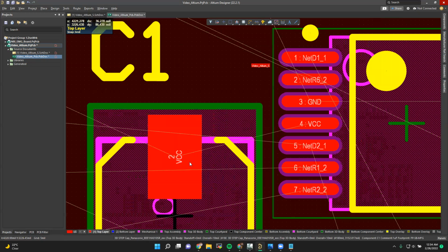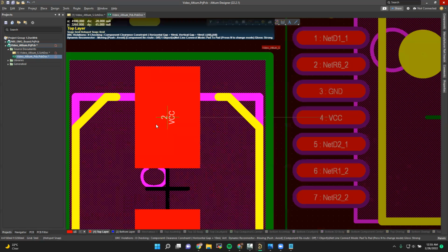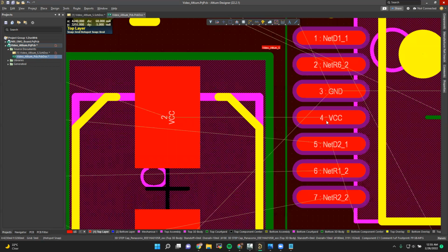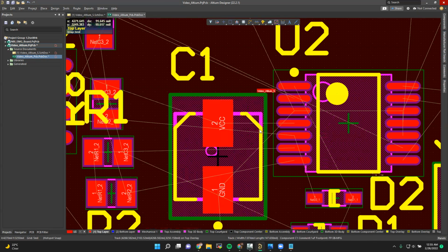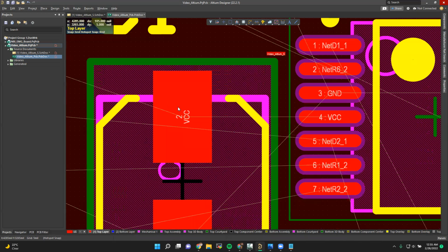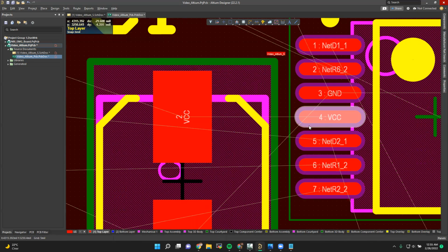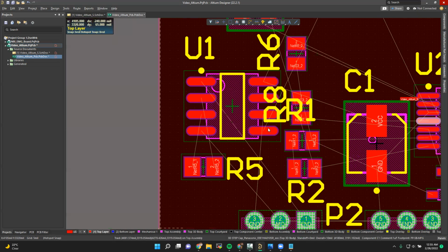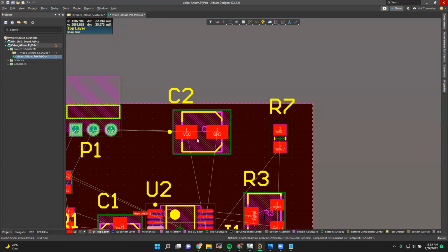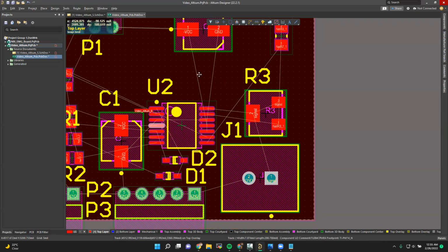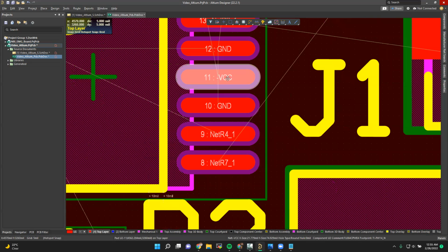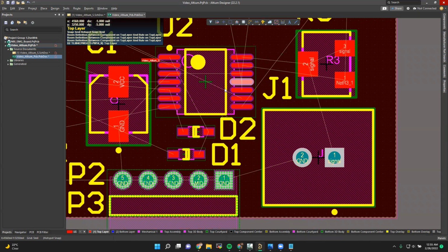So this is going to be better for the design, because you can see now my VCC is here and the VCC is here. So I only need to make a trace from here to here. There's not going to be as much noise affecting the VCC signal. Well, it's not a signal, the power trace going from here to here. The same with this one, the same with this other capacitor. This other capacitor should be placed as close as possible to this pin number 11, which is negative VCC. Okay,